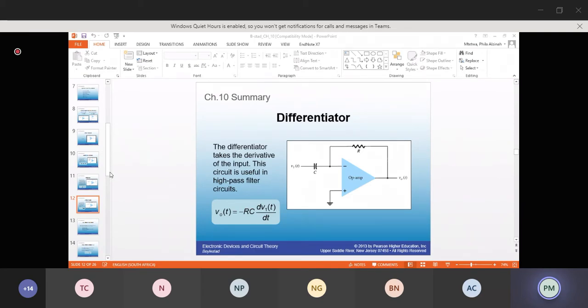After the signal is filtered, it gets fed to the regulator. You have 4 regulators there. You have a 7812. You must remember what a 78 means. It's a positive 12 volt regulator, and be able to identify it in the circuit. Your 4 regulators regulate to plus and minus 12 volts and plus and minus 5 volts, and then you get your output.